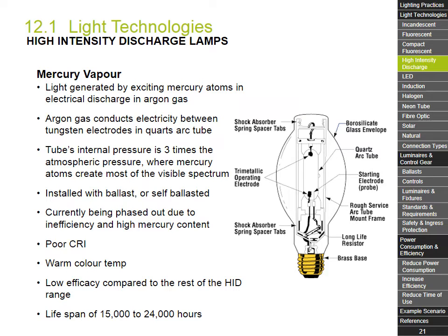Mercury vapor lamps also use control gear, which chiefly involves a ballast which controls the current entering the lamp. They do not require a voltage igniter as they start at 170 volts, which is within the main supply voltage peak. There are also self-ballast models available.